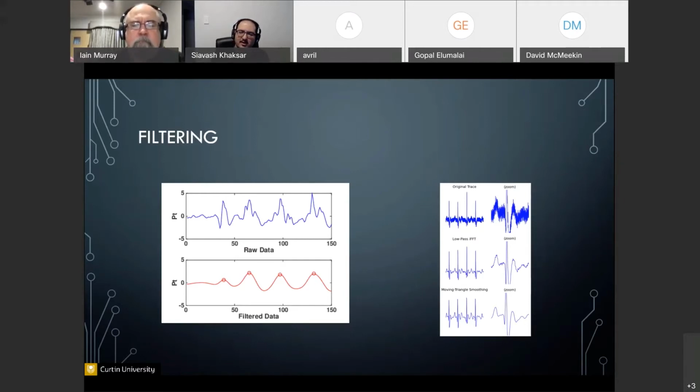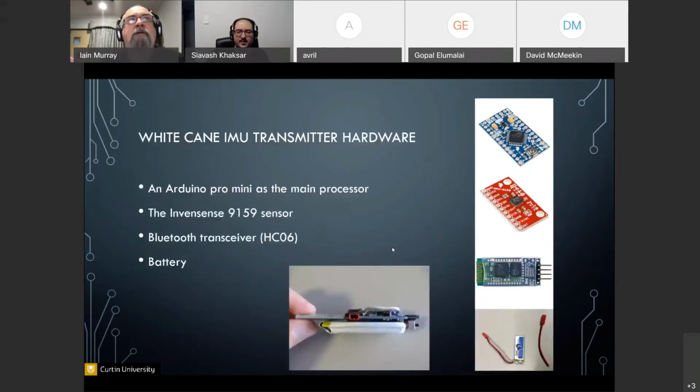these two. And again, IMUs do come with an accelerometer, magnetometer, and gyroscope, but usually the magnetometer isn't used unless it's a very extreme case, because they're very prone to electromagnetic interference in the environment. So we can usually get the work done by just using the accelerometer and gyroscope and getting our orientation that way. Yeah, they're terrible if you've got any metal in the environment. So if you've got lots of filing cabinets inside a building, the magnetometer tends to be next to useless.